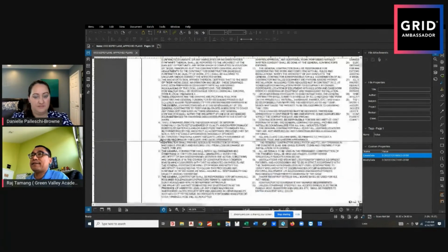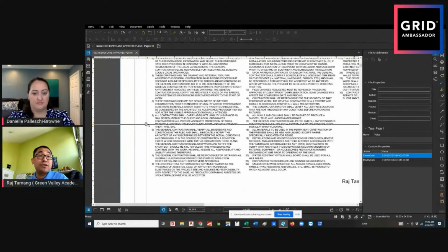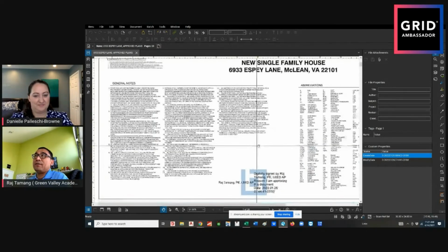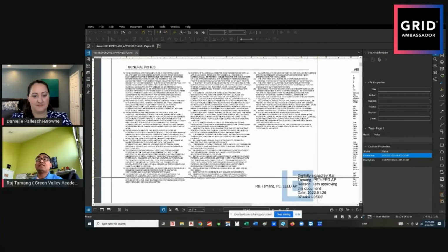I mean, other things you have to make sure of. Let's say when you're digging the foundation, the soil is maybe bad soil. We don't know, right? Because you find out once you're digging the foundation. If it's bad soil, you cannot go in and quickly start putting in the foundation. You have to call the engineers and owners, hey, we have some issue here, and try to correct it. So if they don't call us, we don't know. Yeah. So things like that. Mostly, broadly, I would say this is more good construction practice, right? But if they're not honest, there's nothing you can do.